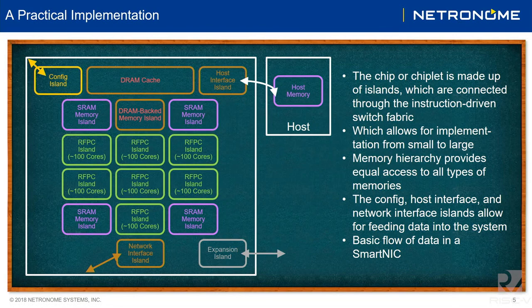Once the SRAM has received the packet, a transactional memory unit that controls the flow of the packets assigns it to a processor. It will autonomously push the appropriate amount of metadata and the first n bytes of the packet to the assigned processor and wake that processor up for processing.